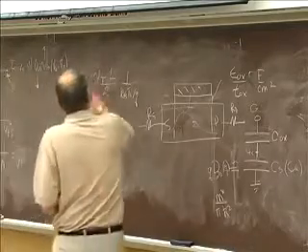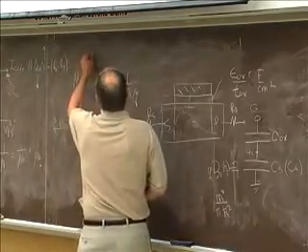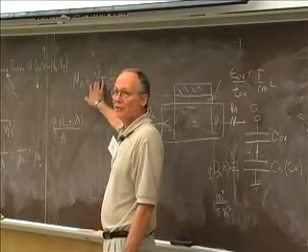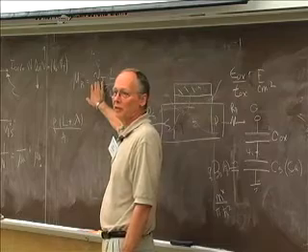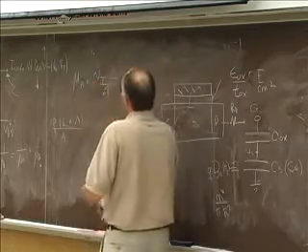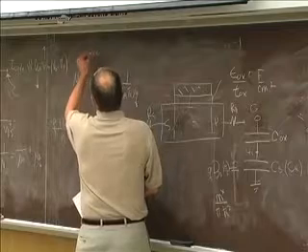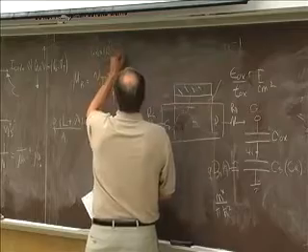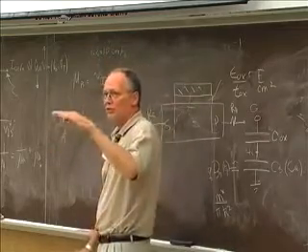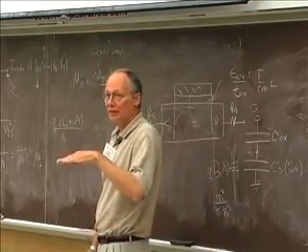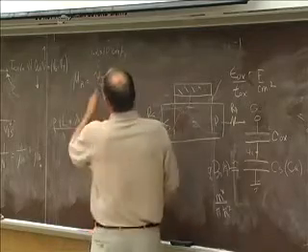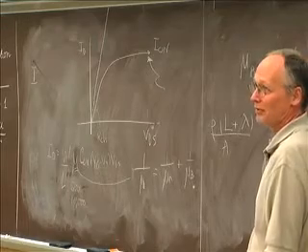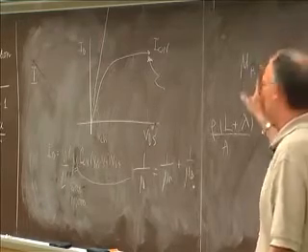Oh, this velocity here? So in silicon, one of the things I really should have said is that this depends on where the Fermi level is in the band. When you're a non-degenerate semiconductor, it's independent of the gate bias, and it's 1.2 times 10 to the 7th centimeters per second. When you start pushing the Fermi level up in the band, that velocity gets higher. So under typical on-current conditions it's higher, but we have to think about what the effective mass is in graphene, but similar things happen.